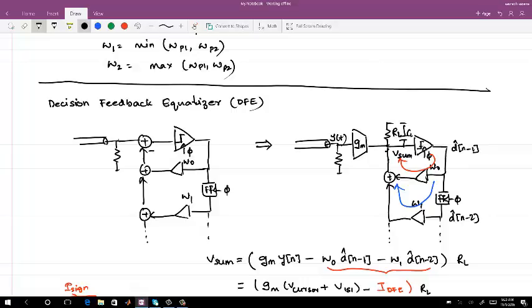Now, tuning to exactly 1 unit of delay, the best way to do it is to use a flip-flop which is clocked at the data rate which you want, so that at every clock edge, you actually change the output. But in all practical circuits, as soon as you clock the flip-flop, your output will appear only after a certain delta time,